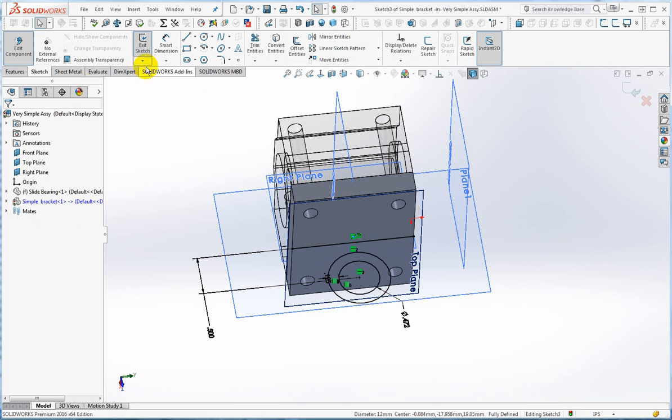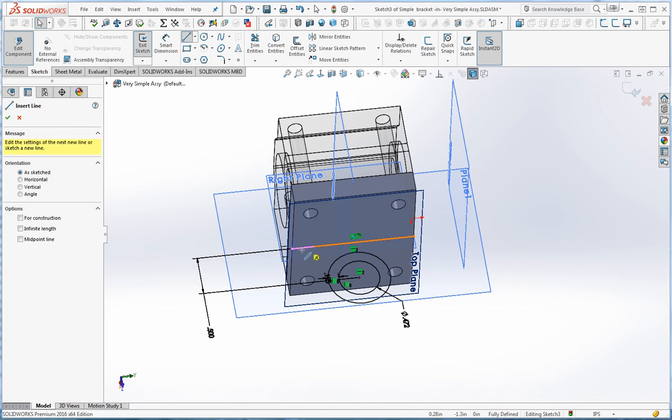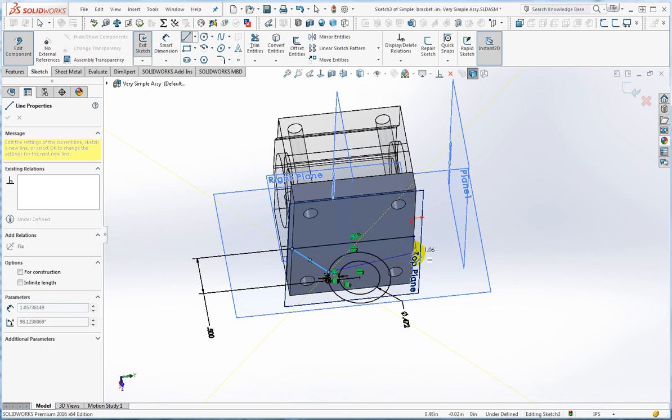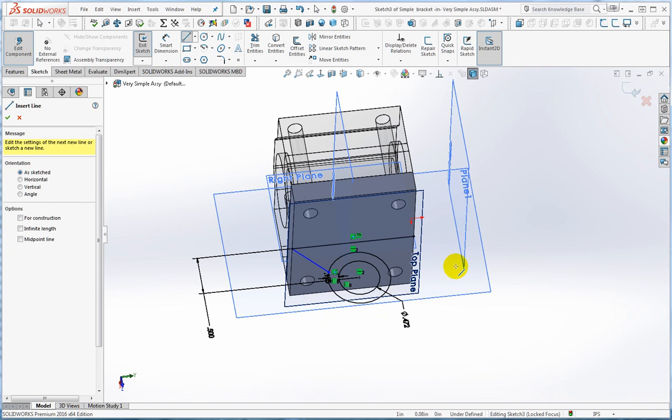Let's continue on. I'm going to draw a line from this corner. Now my goal is to eventually make it tangent to this circle. There are some automation things that will happen. Personally, I prefer not to use the automation because sometimes the automation doesn't really help. So I click in a place where no gridding, no constraining, no snapping has occurred. Then I double click to finish that line.